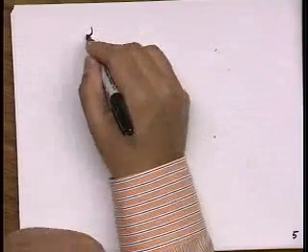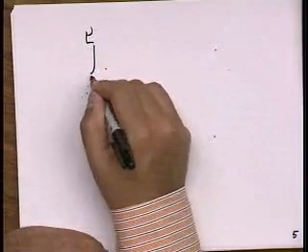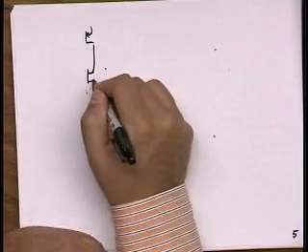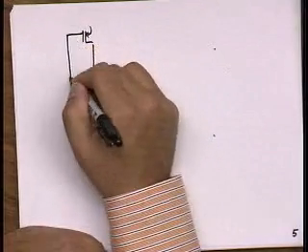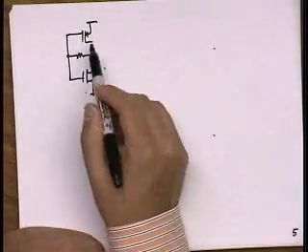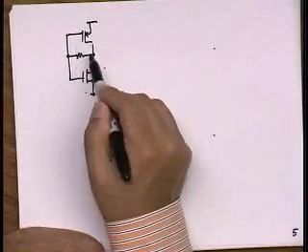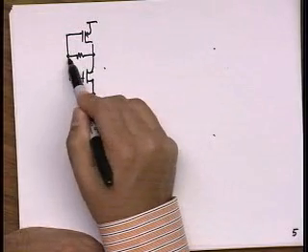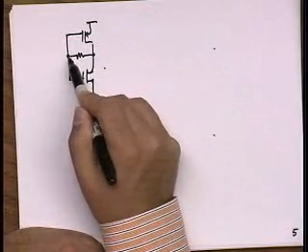Okay, Michael? Yeah, just a resistor between input and output. Yeah, you don't even have to design a loop. You just use some shunt feedback. Because the DC current through the gates is 0, so whatever voltage is at the output, this resistor forces the voltage here to be the same.